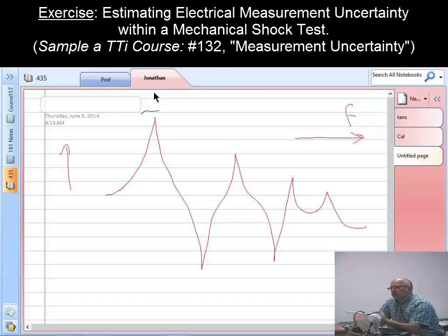In the days of 8-bit A to D converters, which was kind of early 80s technology, around about when the first A to D converters came out, 8-bit didn't last long, soon to 10-bit though. With 8-bit, we would be lucky if the dynamic range was sufficient that we could get down about here, maybe include those. And the consequence was the signal would come down and then it would look like this, and then it would go back up again.